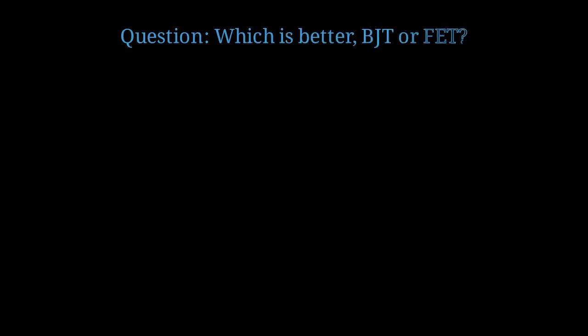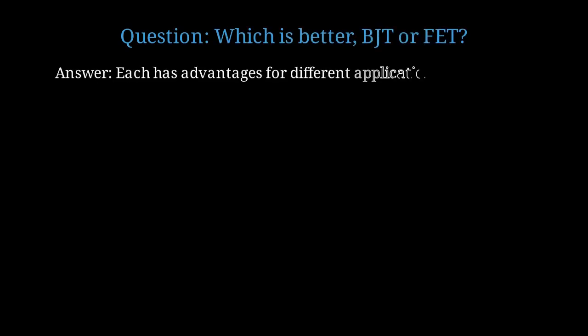Students often ask, which is better, a BJT or a FET? The answer is, neither is universally better. BJTs have higher transconductance and are better for analog amplification. FETs have higher input impedance and are better for digital switching and low-power applications.